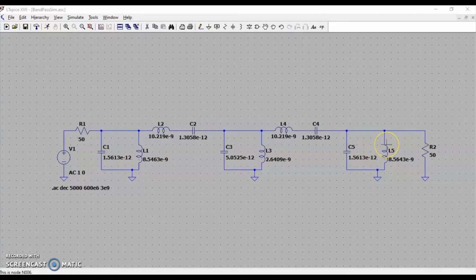So the first step, after defining that, we then define a low pass prototype, which defines a low pass filter with a cutoff frequency of 1 radian per second for the number of elements that we want. And then using those values, we can scale the frequency and the shape of the pass band to go from low pass to band pass to high pass to band stop. We can use techniques to scale the frequencies to get the frequency cutoff and to get the filter that we want here.